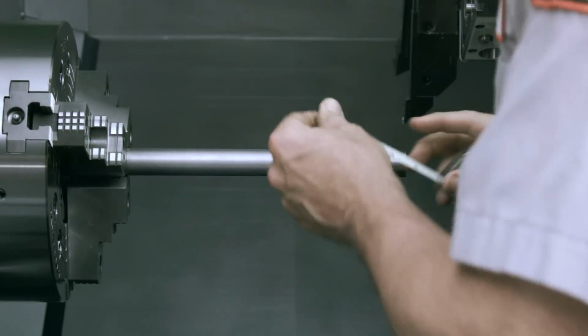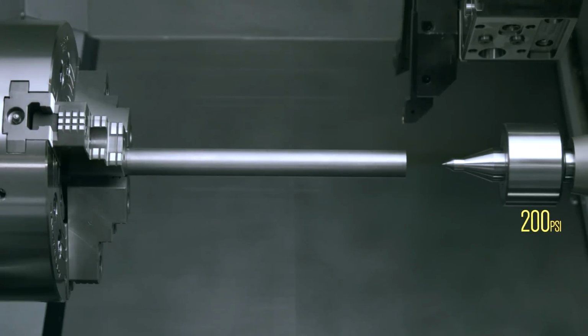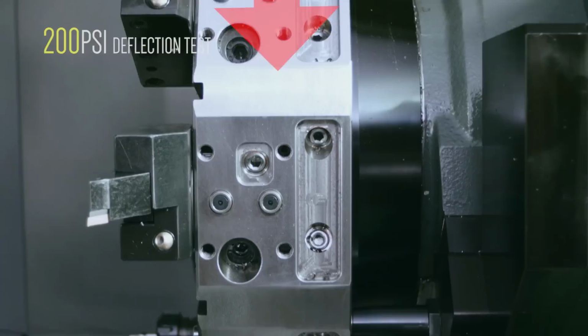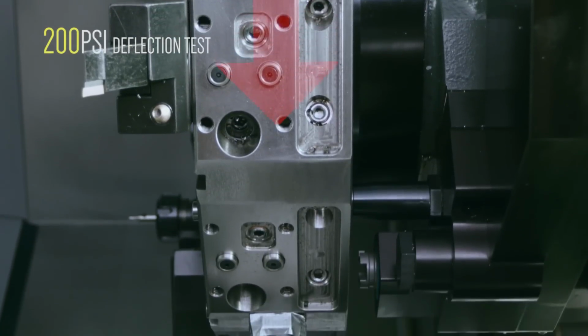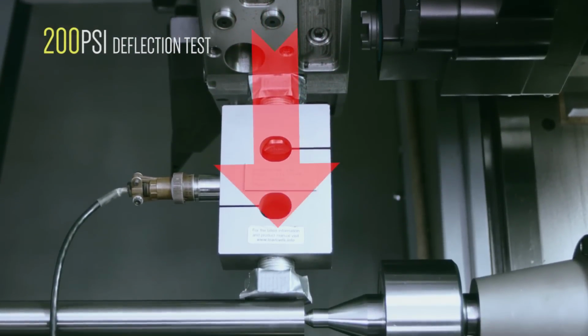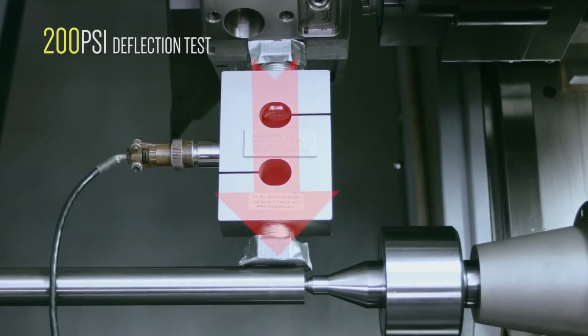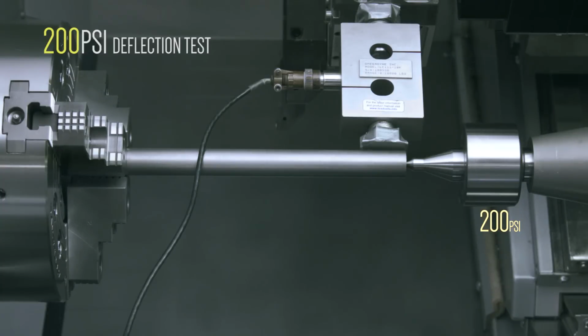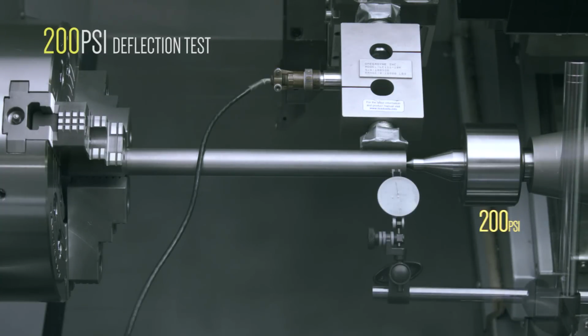We've got this 1-inch diameter shaft held 10 inches out from the chuck, with the tailstock clamping it at 200 psi. To simulate a cutting force, we'll use the X-axis to push with the turret against the load cell, which in turn will push against the shaft. And finally, we'll use an indicator to measure how much the shaft deflects as the load increases.